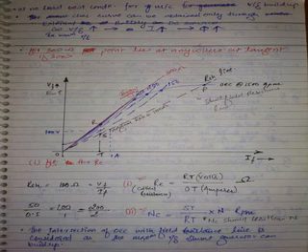I'm repeating again. Length of RT, this one, represents 1500, the original rated speed, the given speed. Length of ST represents NC. Just put it like an equation here, mathematically. Length of RT represents rated speed or given speed N. Length of ST represents NC. From this, mathematically, you can write RT by ST is equal to N by NC.